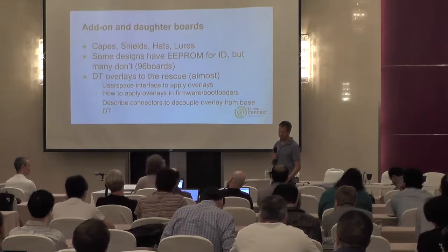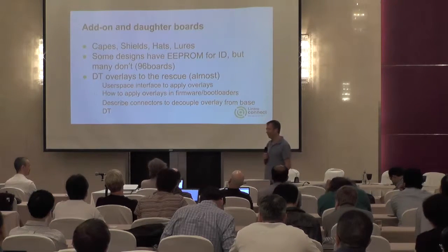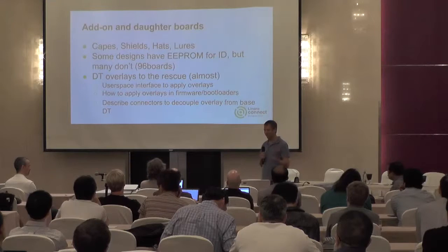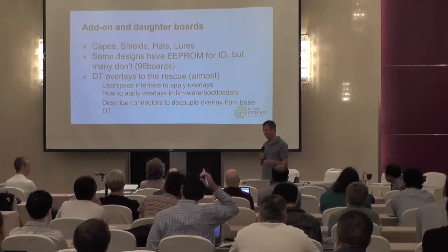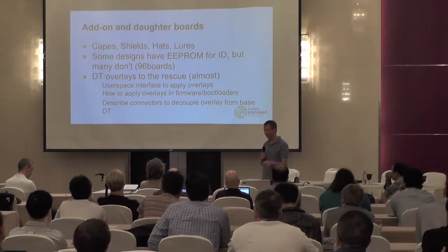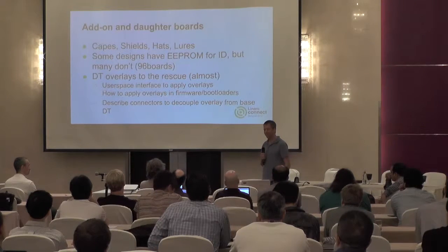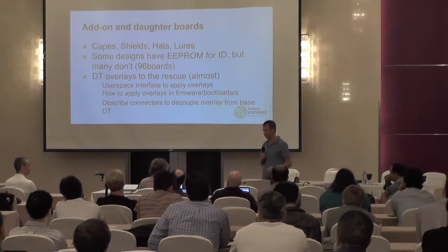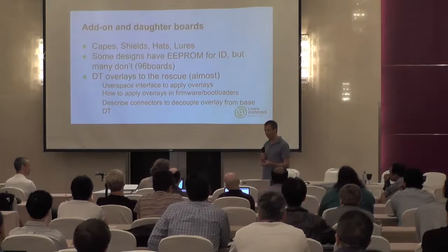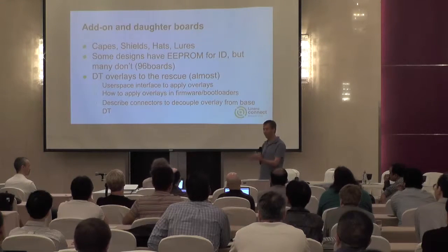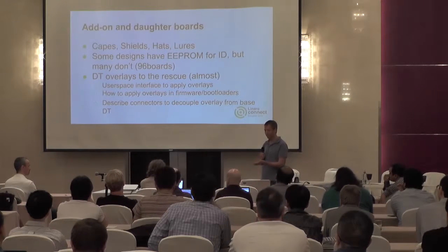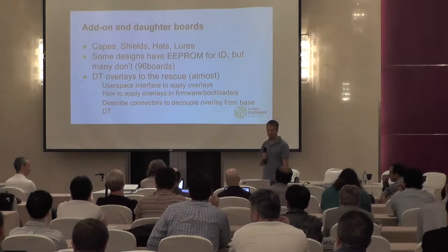And there's also a need to describe connectors on boards so that you can take an overlay for a specific mezzanine board and plug that into different motherboards and apply that to the device tree of the motherboard in a generic way. So the problem there is on one board, the I2C device is on one I2C bus of the SoC, and then on another board, it's on a different I2C bus.